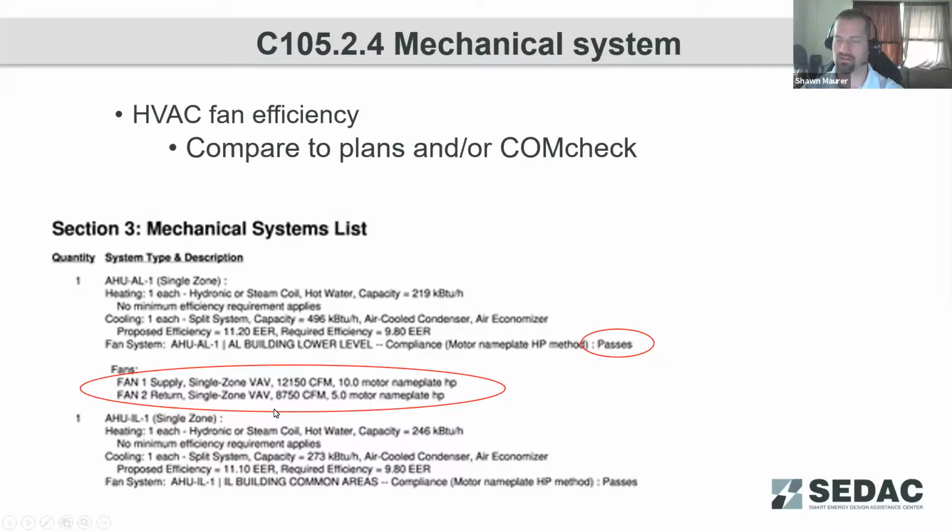So if you don't have tight ductwork and you've got supply leaks into a plenum, especially if you've got open return plenums where you short circuit that supply air directly back to the air handler, that can actually increase the horsepower requirements for those fans by 3 to 5 horsepower if that ductwork isn't properly sealed. And so as the energy codes have become stricter on the requirements for the horsepower of these fan motors, the duct sealing component of the system is also becoming much more important to ensure that these systems work properly.